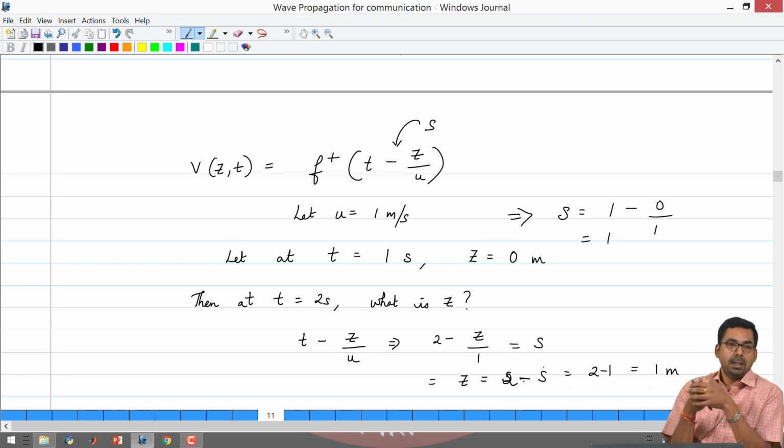Also, there is a voltage wave that goes from your source to the load, but we already know from circuit analysis that you have something known as the maximum power transfer theorem, which says that the maximum amount of power can be transferred to the load only if there are impedance matching or resistance matching conditions. If it is not there, then you will not be transferring maximum power, which also means that the remaining power will have to come back through your transmission line. And so, when we talk about a solution having a forward and a backward wave, usually it means that it is a finite length transmission line and the impedance may not be matched at the load end.